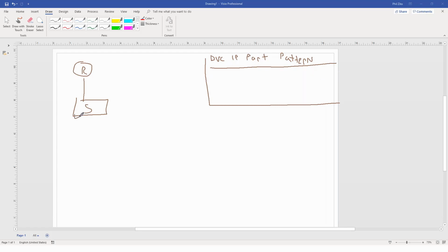Okay, and that's what you do when you're designing IP networks, by the way, for some of you who have never designed an IP network before. You have a list of your devices, your IPs, and sometimes you'll even have your MAC addresses and any other pertinent information as well. So we would lay out, from switch port 1, this would go to our chiller, so CH, and then switch port 2 we would go to our AHU, and so on and so forth.